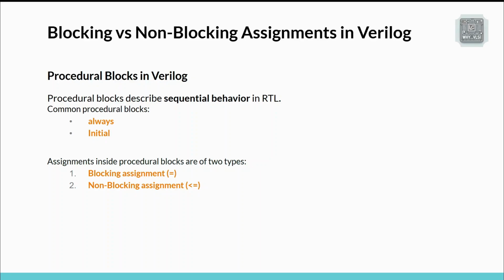The first one is blocking assignment, represented using the equal to sign. The second one is non-blocking assignment, represented using the less than equal symbol. These two assignments may look similar, but they behave very differently during simulation and hardware synthesis. In this video, we will understand how each assignment works, how hardware is implemented, and why mixing them incorrectly can cause serious RTL bugs.